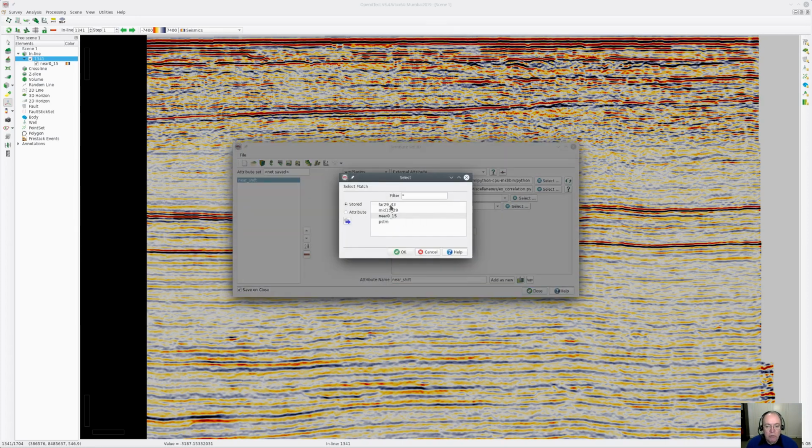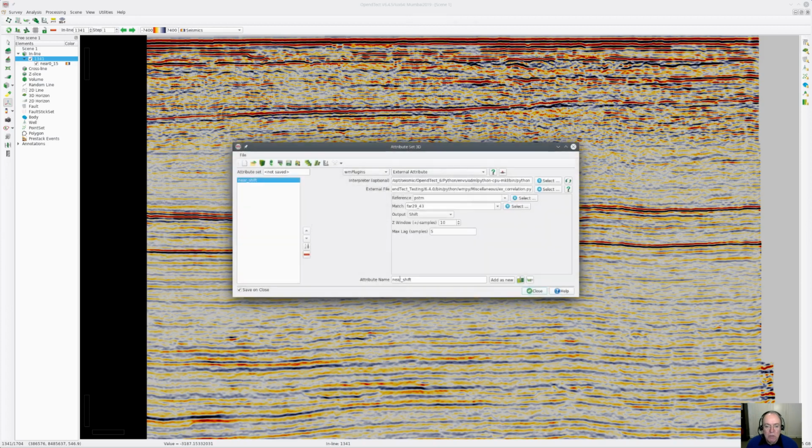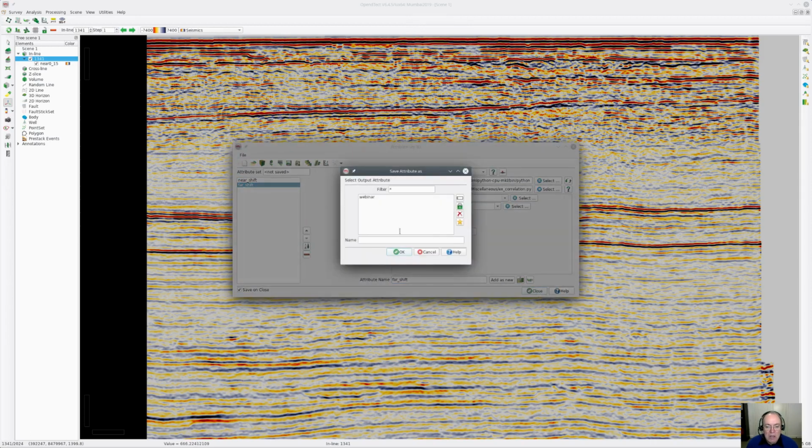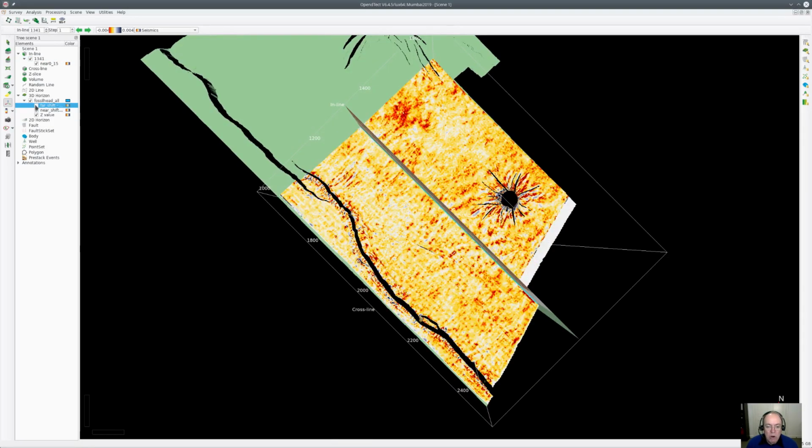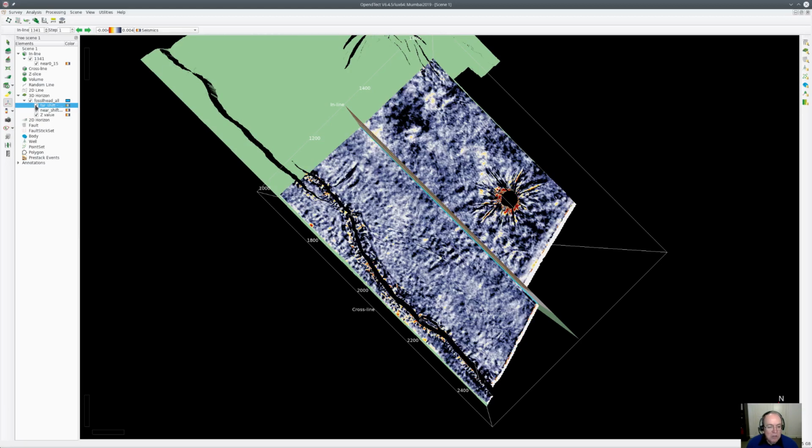It's easy to define attributes to compute these parameters for the near and far angle stacks. These can be assessed by examining them over a few key events in the seismic volume. Here I have already used these attributes with the Processing Create Horizon Output attribute menu to compute them as horizon data. Further evidence that Python attribute scripts can be used just like an OpendTect native attribute.